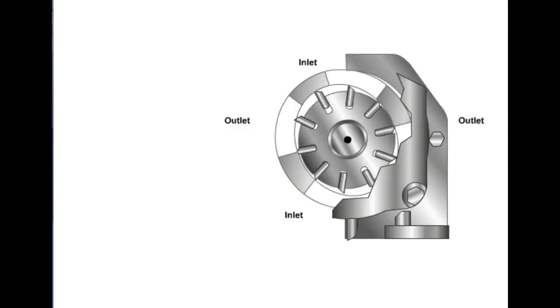It is important before viewing this animation to understand the unbalanced vane pump. If you need to review it, go back and click on Unbalanced Vane Pumps. In the unbalanced vane pump, which has been previously illustrated, one half of the pumping mechanism is at less than atmospheric pressure. The other half is subjected to full system pressure. This results in side-loading the shaft, while under high pressure conditions.